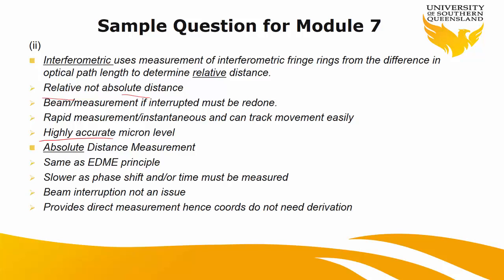Absolute distance is really similar to what you do in total station, yeah? It's not as precise as relative, yeah? But it can be either phase shift or time of flight, as we know, yeah. We know phase shift is more accurate in a way.